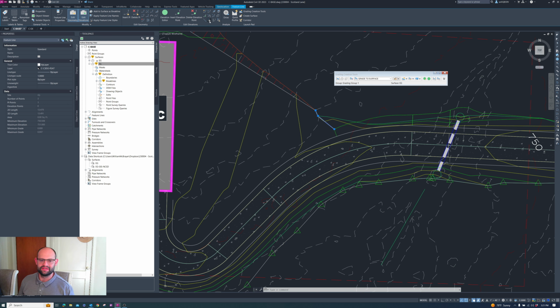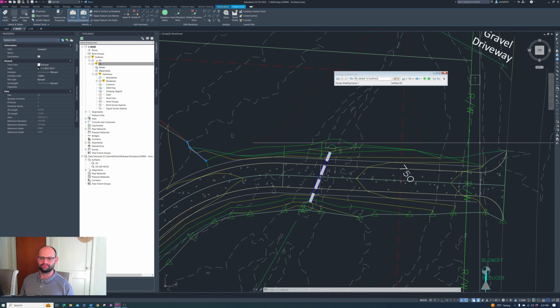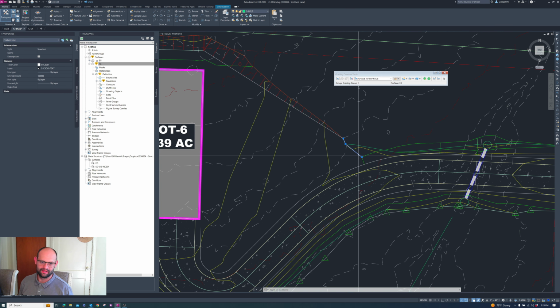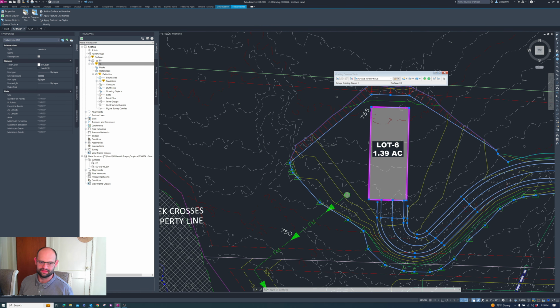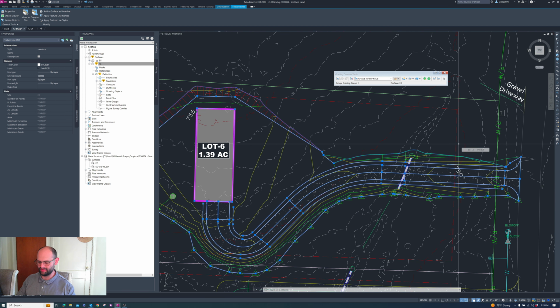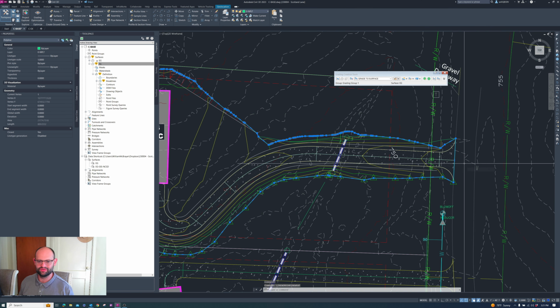Let's not forget to reset to existing on these perimeter feature lines we've modified. Set that one. Double tap this one and this one. Then I'm going to select similar on the feature lines. Click my grading group perimeter pieces. I think that generates everything we need to enclose it. So LINEWORKSHRINKWRAP. We have a perfect closed boundary again. So let's add that to the surface.